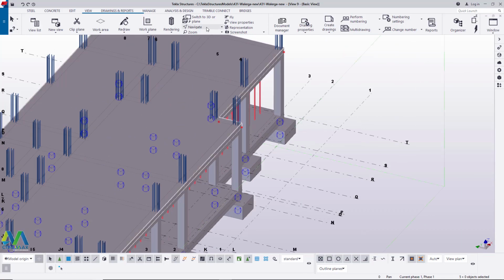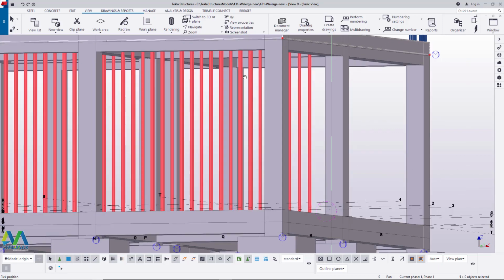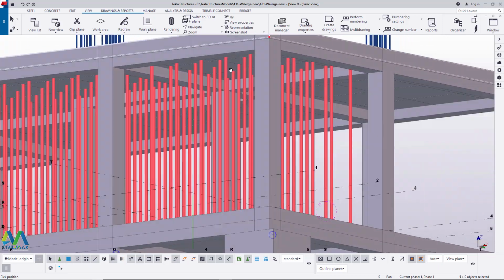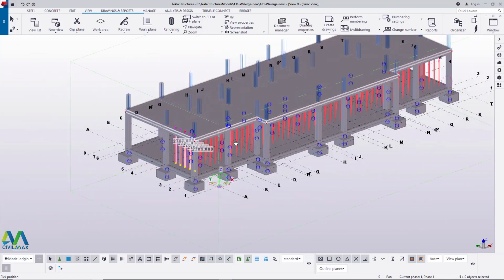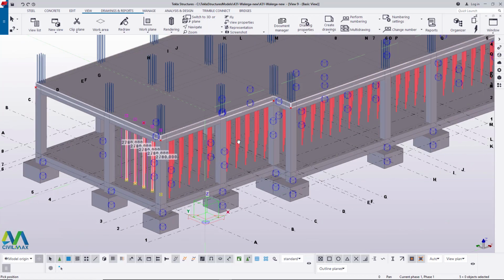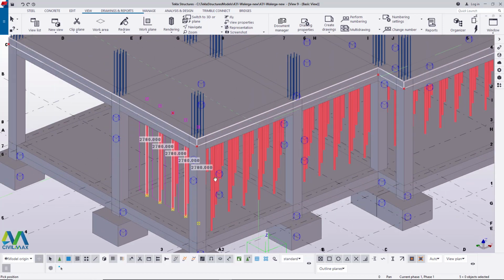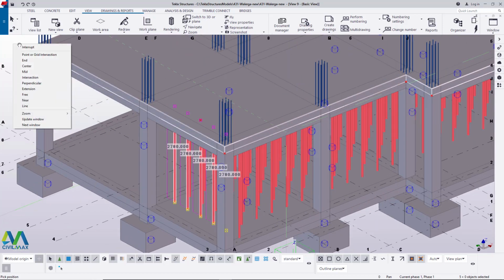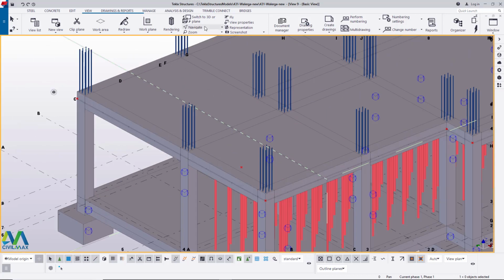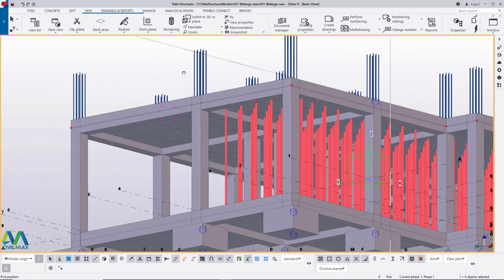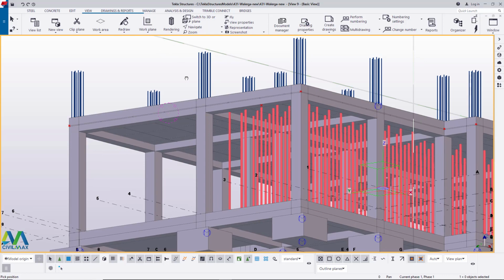Now if we move all the way to that end, we can see that our steel props are properly arranged at the bottom of these panels that will be supporting our slab during the casting. Now that is option 1. We can also use the scaffolds. The scaffold can also be used in supporting the formwork panels.